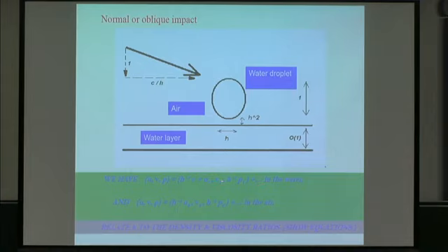So in the water, we expect the vertical velocity to be order 1 because of that definition of the incoming speed. By continuity, then u is order 1 because x and y are comparable in the droplet. And then the pressure we expect to be order 1 over h, so a large pressure, so that the pressure gradient dp is of order h to the minus 2.